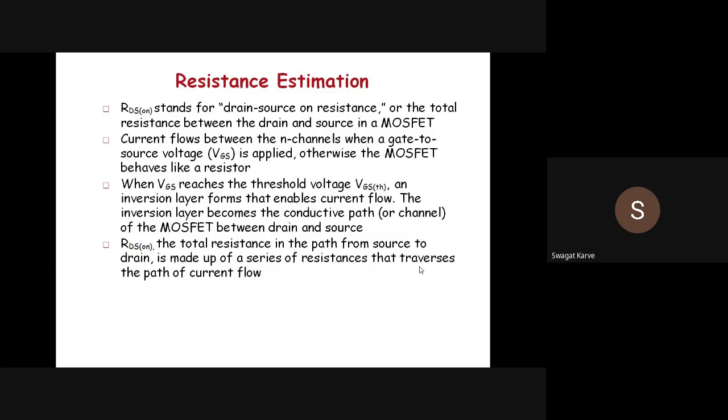a series of resistances, right? And what will contribute to these resistances? Its geometrical structure, different layers. It is not the case that there is only N-type and P-type material. Along with that there is an oxidation layer, the SiO2 layer, and some sort of terminal to connect the transistor to the supply; you require some sort of connection or terminal point. Then you require different oxidation and insulation layers.